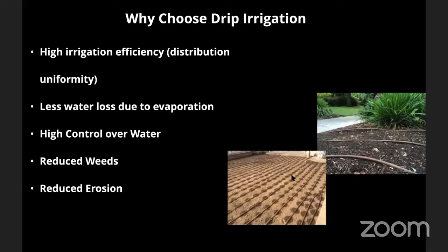If there is a way to set an area this big that's all similar water demands, depending on the heights of the plants, up for a very high efficiency spray system, with a different design and different spray nozzles than a traditional spray system with a lot of misting, like rotating sprinkler nozzles, I might do an area that large with that approach, depending on the plant height. If the plants are too tall and those sprays would be blocked, I'd go with drip. So that's one advantage, especially coming from a sprinkler system. Sometimes it's easier to convert to that high efficiency spray. Sometimes drip is better, but that's one consideration.